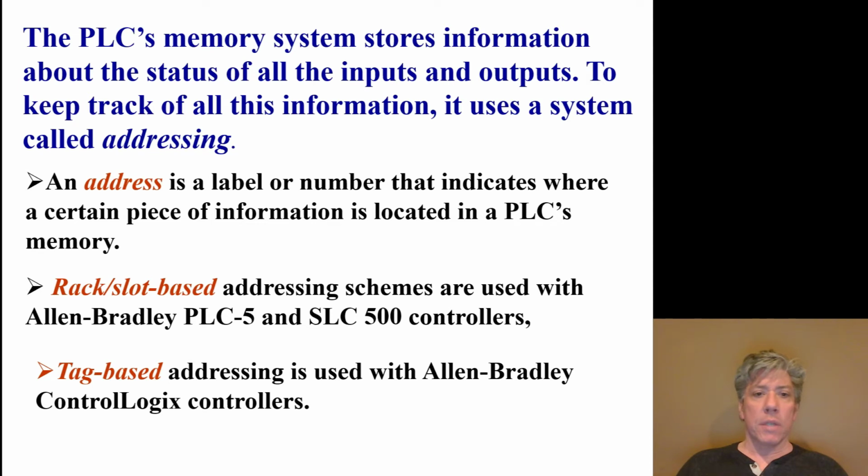in the PLC's memory. Now, sometimes they'll use what's called rack and slot based, and this is common on Allen Bradley PLCs, where you have a rack number followed by a slot number essentially, and then typically a bit number as well. But tag-based addressing is used with other Allen Bradley and ControlLogix controllers, where basically the input or output is named, but that name is associated with a very particular address.